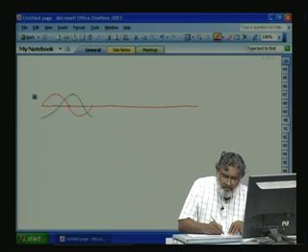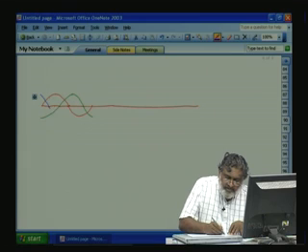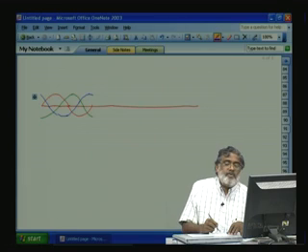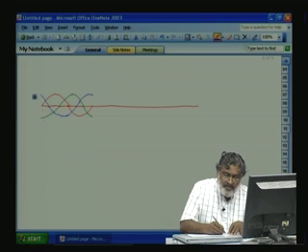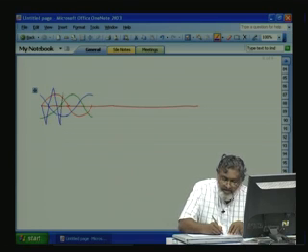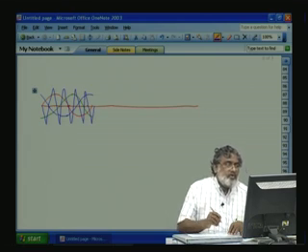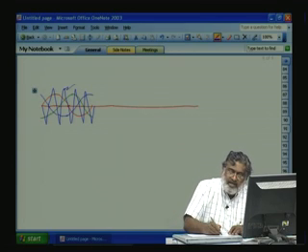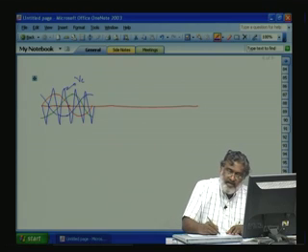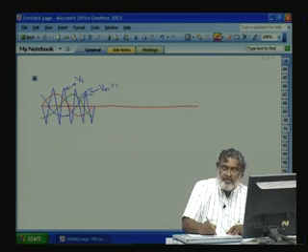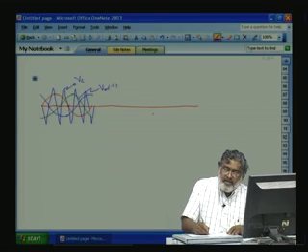Okay. Now this is the C phase. Now we will compare this with a fixed triangle frequency. So the triangle will be a high frequency triangle waveform. See here, for motor drive applications, this is called the carrier wave, VC, and these are the modulating waves VMT. So 3 phases. So for the inverter we have the 3 legs like this.